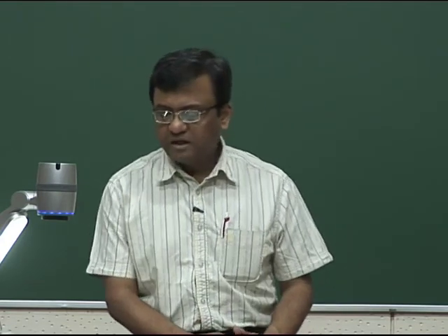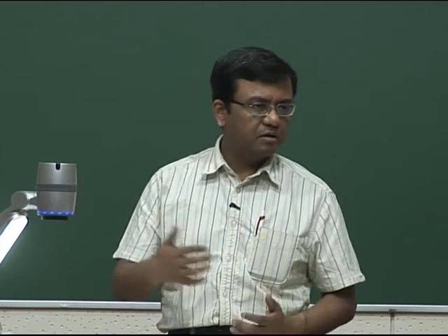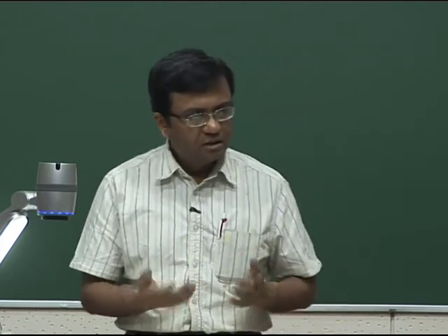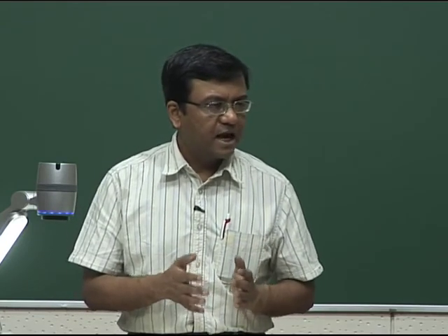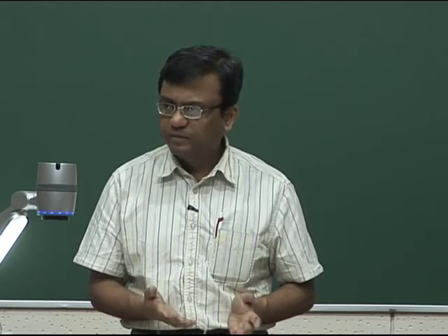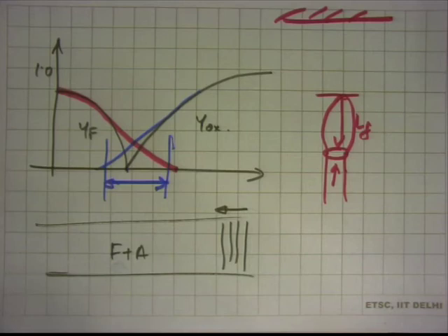Okay. In a transient sense, when you have fuel and oxidizer and you are igniting it, then in that short period of time there will be a flame which will just move and settle at the phi equal to 1 surface. That movement is there, but otherwise there is no fundamental tendency of a diffusion flame, a non-premixed flame, to move like that. So there is no fundamental burning velocity. And in any case, what I was telling you is that if you do m dot divided by rho A to get the velocity, that m dot is that of the fuel, so it's not a mixture property anyway. Okay, like laminar premixed combustion, that was a mixture property. Laminar burning velocity is a property of the mixture.